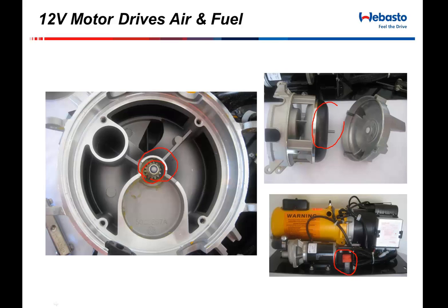If you turn the heater off instantly, obviously everything shuts down. The bad part of it is you have a lot of heat built up inside of this heat exchanger. That heat will radiate very, very quickly and will generally burn out that melt fuse, that double white wire that's sitting underneath it.